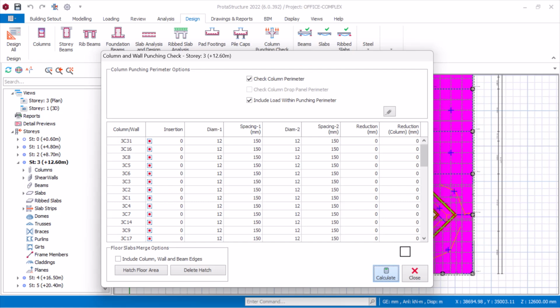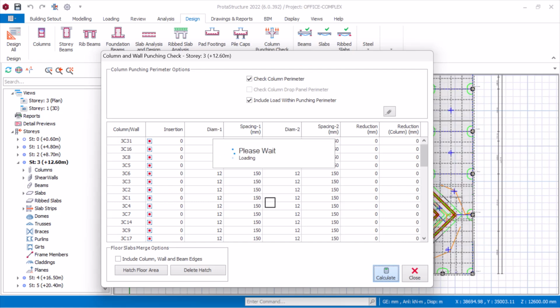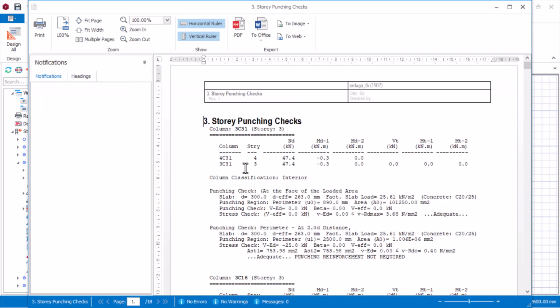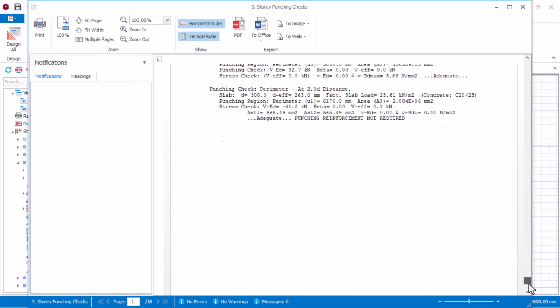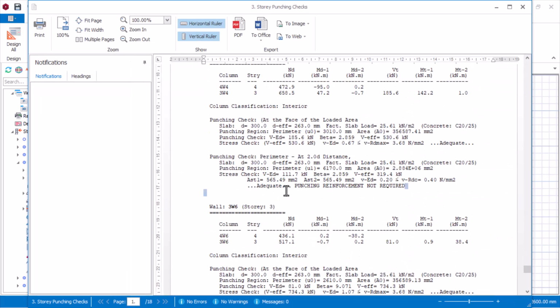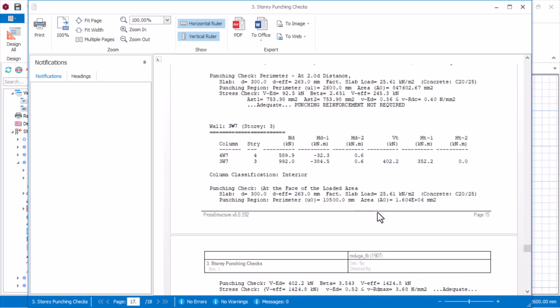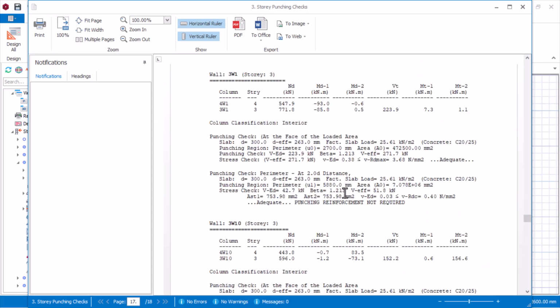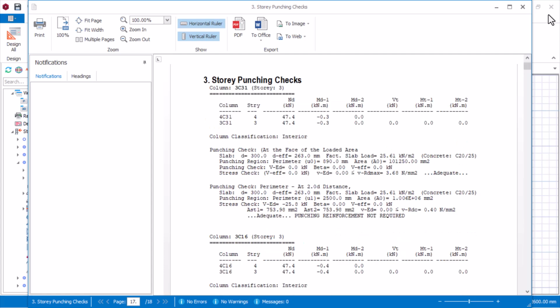So either the flat slab without column drop or with column drop, one of their major failure zones is punching. That's why the punching check is very, very crucial when it comes to flat slab design. You must take that into consideration.